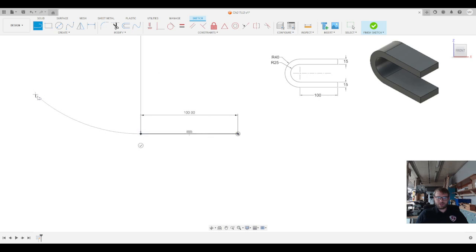And when I click and hold, I get this arc. Okay, so when you create a line, you click and hold, your next one is going to be an arc that is tangent to your previous line. So if I go here and click and then go here, well, actually, that one isn't necessarily tangent, but your one after you do a line and then you click is going to be an arc tangent to that. So I'm going to hit Control Z to undo back to here.